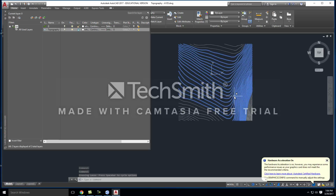I would highly recommend that before you start really kicking off drawing on your floor plan, and if you're going to be working on this file, you lock the topography so that you don't accidentally move any of those lines. You might think, what are the chances of that happening? But the second that you think about that, it will happen to you, and you're going to be wondering how to get it back. So locking is an option. You generally pick that once you know you don't want something to move anymore.